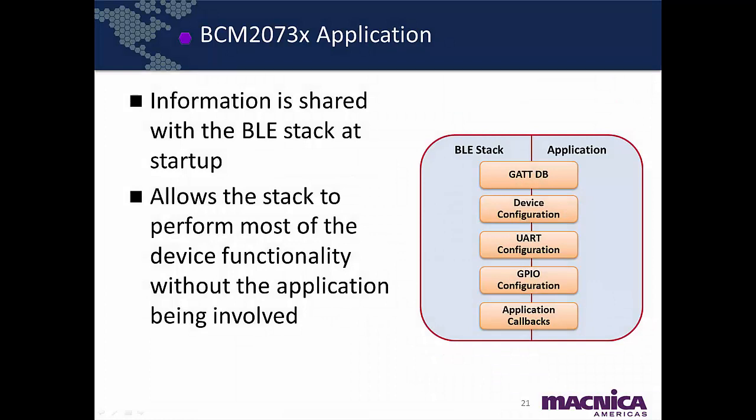With our newly gained understanding of how a BLE device application and a client will communicate with one another, what are the specific parts of the device application? Recall that the Broadcom smart devices utilize internal ROM to execute the BLE stack layers. Now, the device must be properly initialized at power-up so that this ROM-based code will function properly and handle almost all of the communication and data transfers without the application having to be explicitly involved.